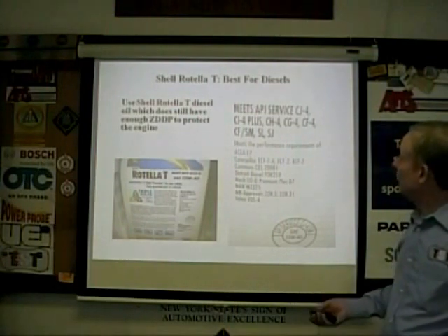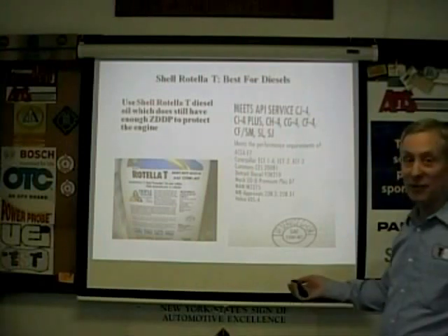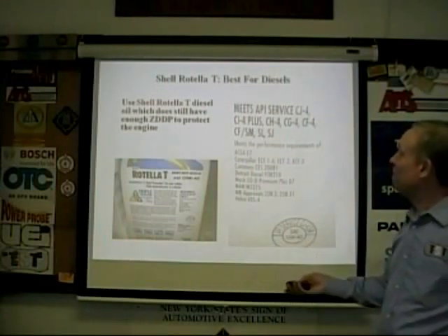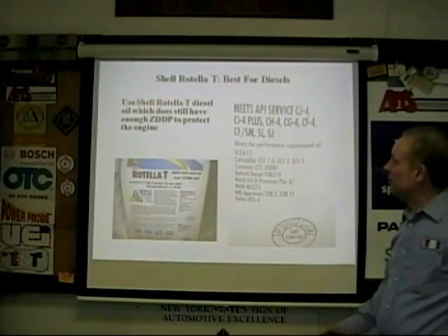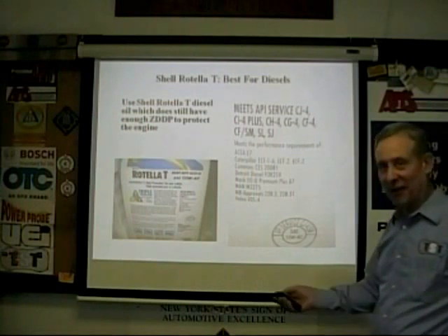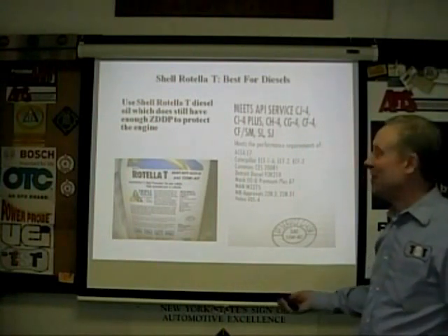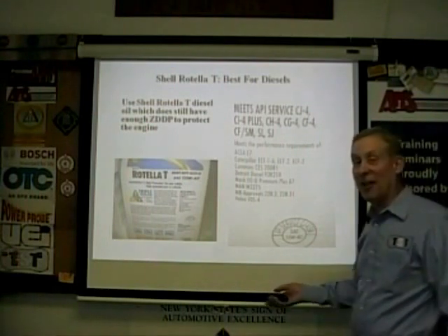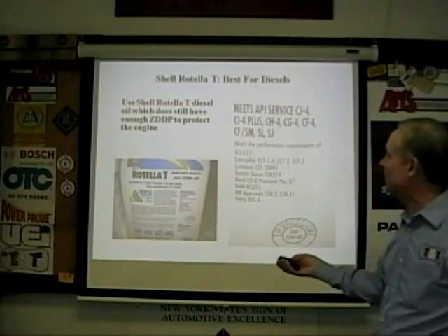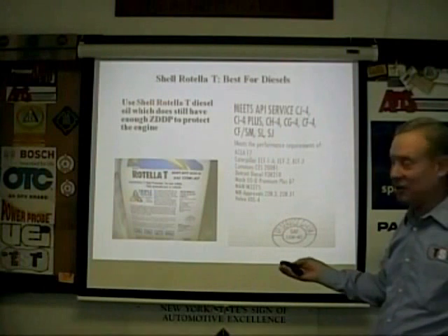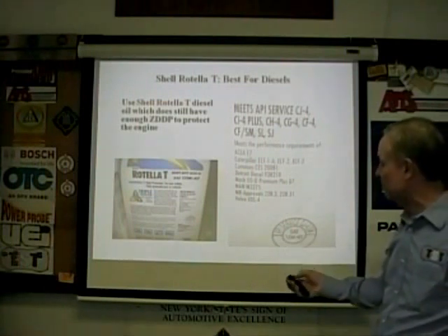Shell Rotella, best for diesels. This is great stuff. I use it in my backhoe. You've got to use Shell Rotella diesel. It does still have enough ZDDP, a chemical name I still can't pronounce, but it's a zinc compound molecule that's used as a kind of slipperiness enhancer. It protects the engine against very high loads like you find in diesels.